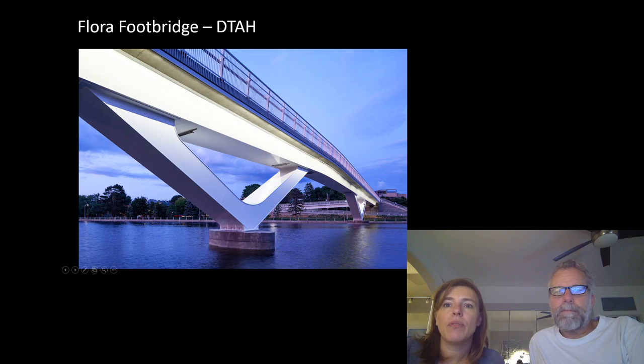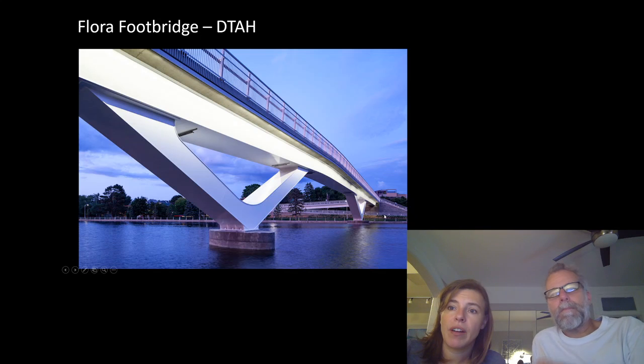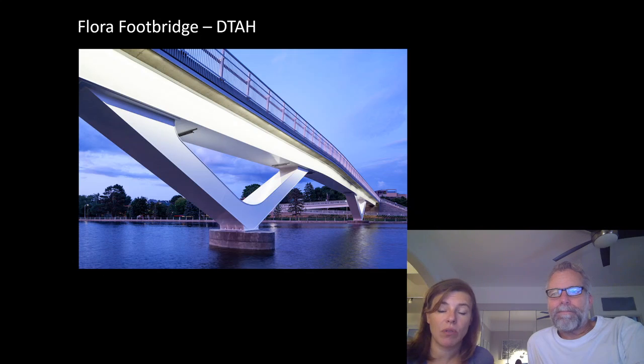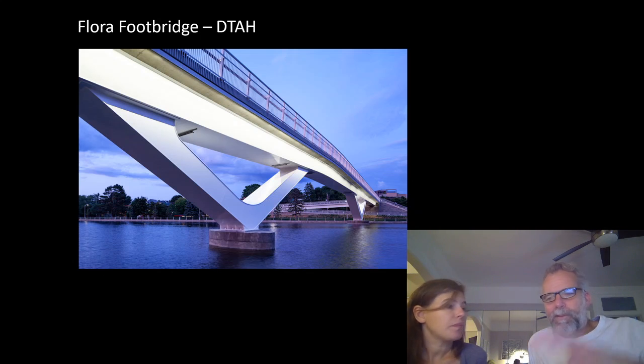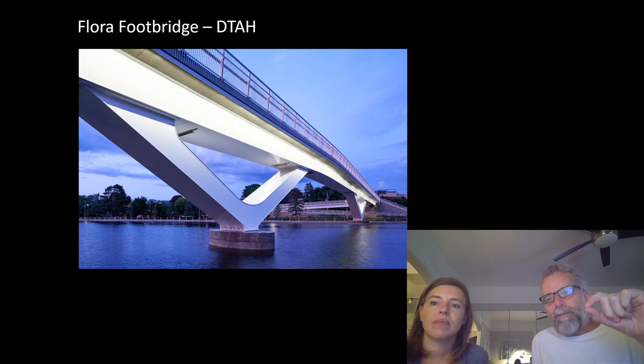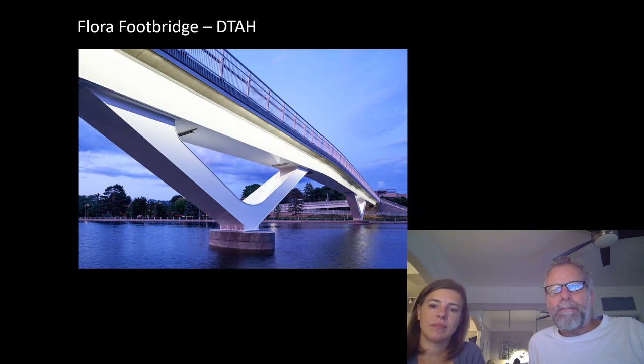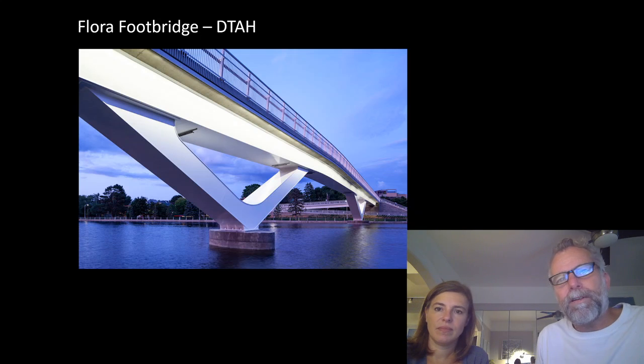Dave talked about if you raise the bridge up, you need to get to the bridge. Look at the ramp needed to get up to the height to enter the bridge. The stairs are over here. This is the ramp required. It's almost as long as the bridge itself to get up to the bridge height so that it's accessible. So you can see the minimizing structural depth becomes a real thing. Every foot of structural depth corresponds to 20 feet of ramp, so making the depth shallow makes a huge difference.